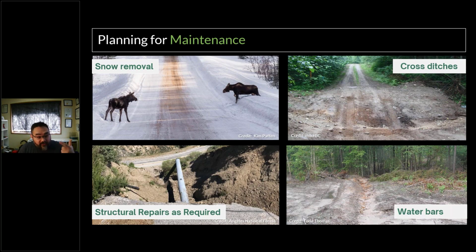So if you're going to be down for a while, you can plan for those things and do them before it becomes an issue. And I can tell you that seasonal deactivation with road surface erosion is far more expensive to deal with after it's eroded your surface, rather than have an excavator cut in some water bars.